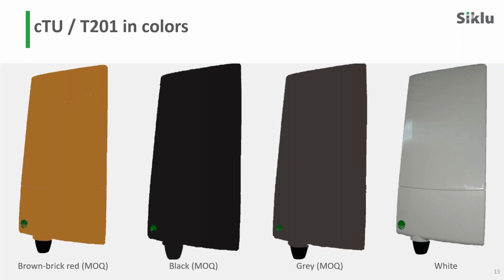I see here a question about the elevation profile. So the coverage angle of the antenna is plus minus 10 degrees vertically. For the TUs, for the compact TUs, and for the BUs, all of our units, it's the same performance. As I said, we try to keep it uniform across the portfolio. Plus minus 45 degrees horizontal, plus minus 10 degrees vertical.